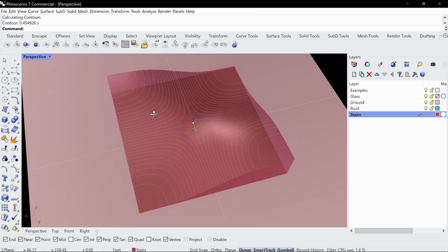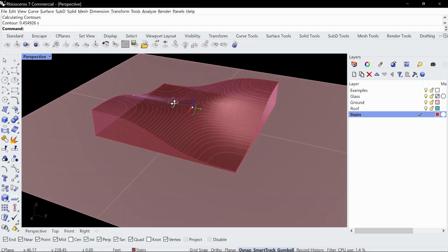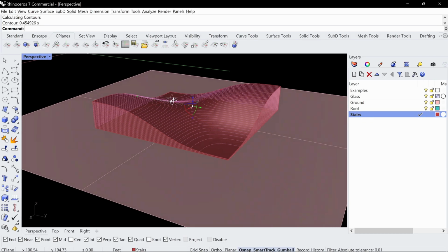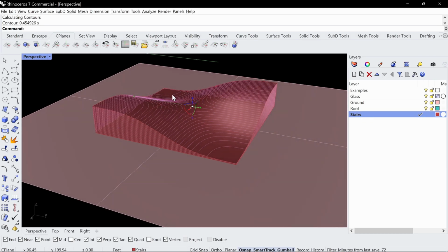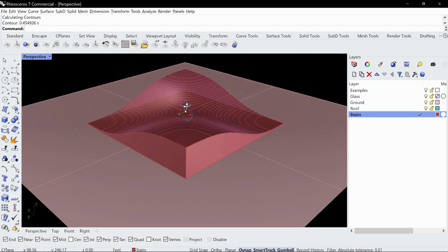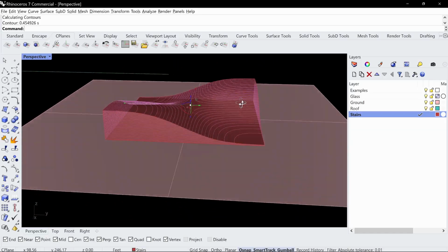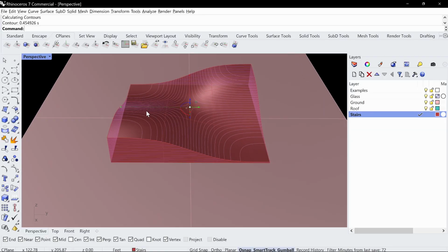All right, cool. If you notice, the reason why I'm using 7 inches is because, at least in the US, maximum riser height is 7 inches. It depends on jurisdiction, but mostly maximum riser height is typically 7 inches. You can do 6 inches. But currently what we have here are these steps. So I'm going to go ahead and group it.